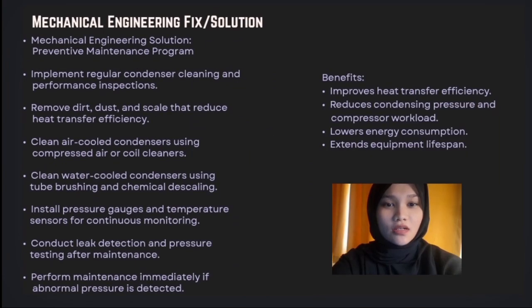The proposed engineering solution is a preventive maintenance program that includes regular cleaning, pressure monitoring, and performance inspection. Fouling reduces heat transfer efficiency, causing higher condensing pressure and increased compressor workload. By cleaning the condenser surface regularly and installing a pressure gauge and temperature sensor, problems can be detected early before unsafe conditions occur.